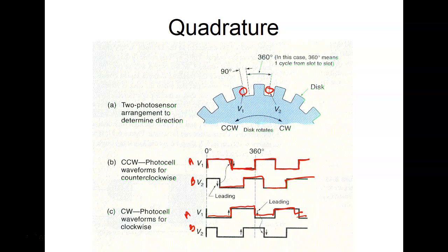So that's the way the robot goes. It's got counters on the encoder. If you ever actually look at the encoder, it's an electronic circuit card, and it's got counters on there. And of course, robots can move up or move down, so those have got to be quadrature encoders, so it knows which direction to go. So it's got the counters in there as part of the encoder.